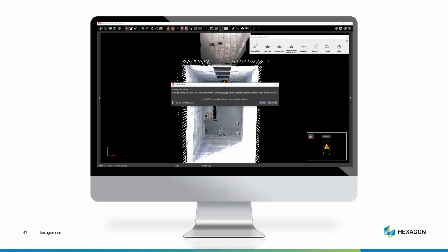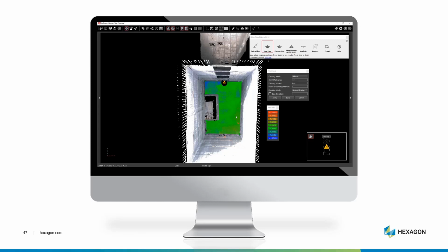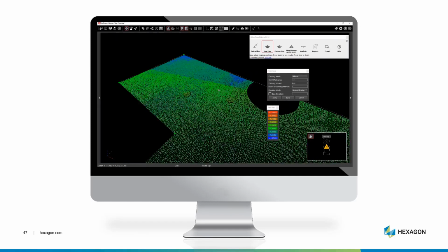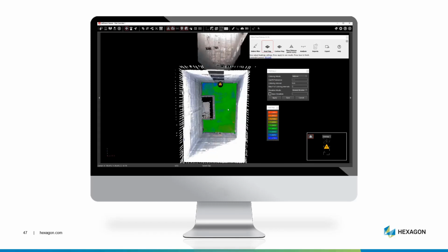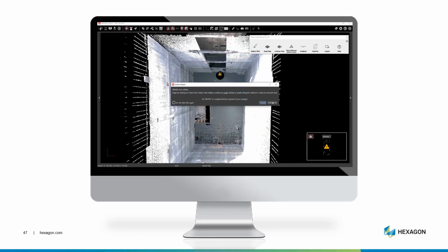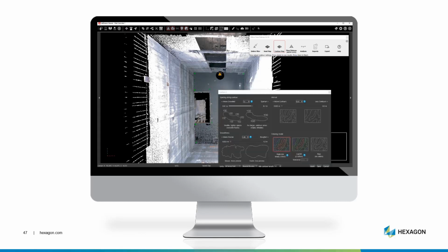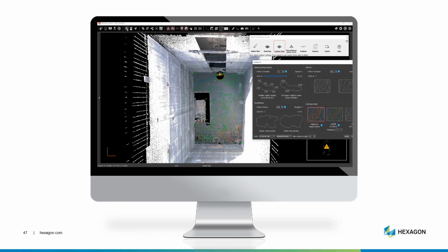So we click the plugin icon and we open up the Rhythm application from the loaded plugins, and then we go basically left to right across this small toolbar that's popped up, so we can remove debris. Then we can run a heat map on there. Then we can create a contour map. Then we can do our floor flatness analysis, and then ultimately the end result is that you're going to produce reports which you can share with your end users or share with people that need that information.